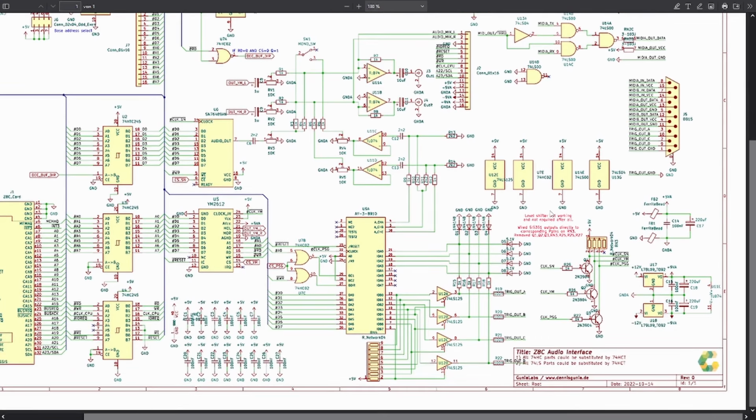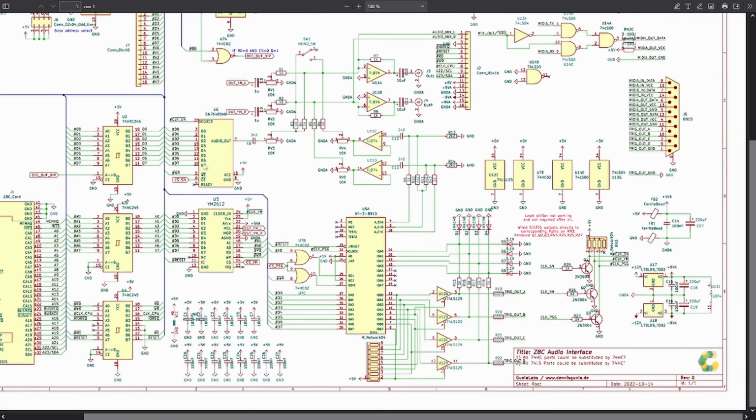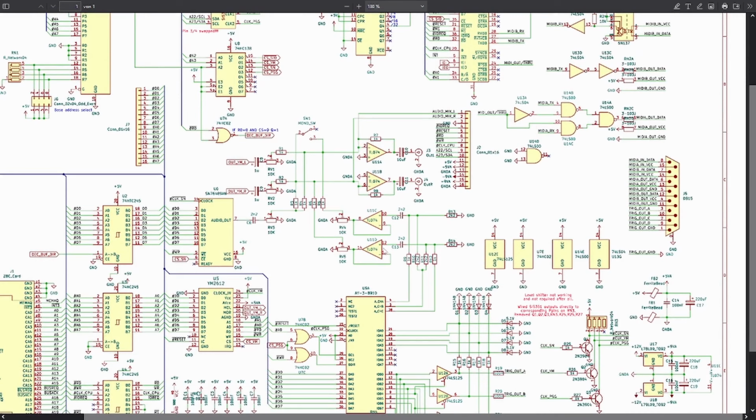Okay, then there are the sound generator chips themselves, the SN76489, the YM2612, and the AY-3-8910. These all generate individual signals, which are then mixed together. The one issue that I faced here is that the old chips generated different outputs. For example, the YM2612 had a stereo output, the SN76489 has a mono output, and the AY-3-8910 has 3 individual